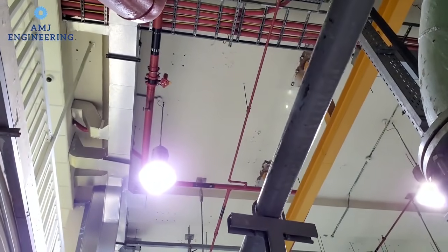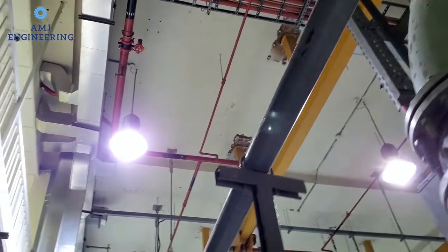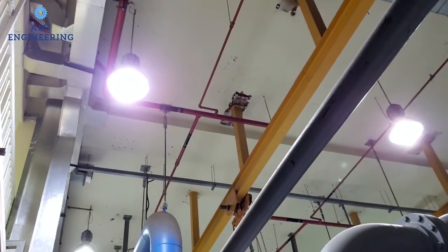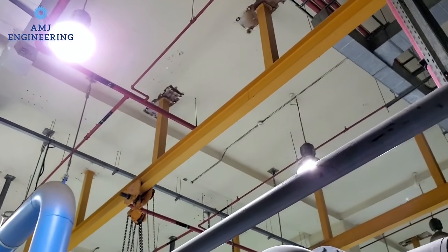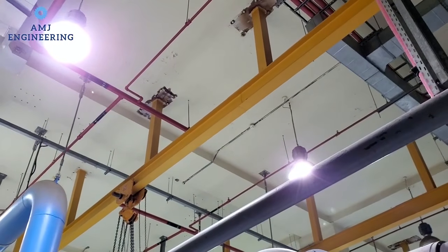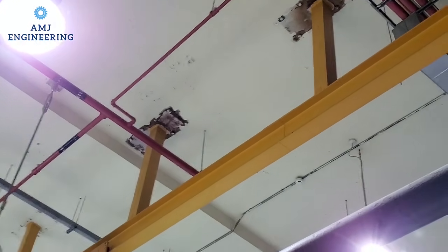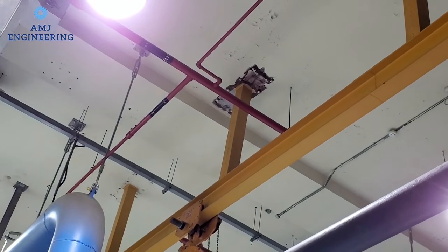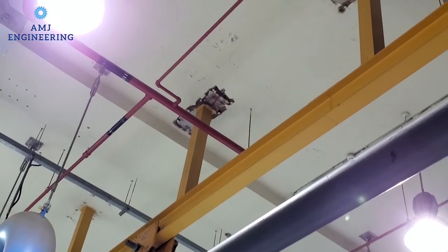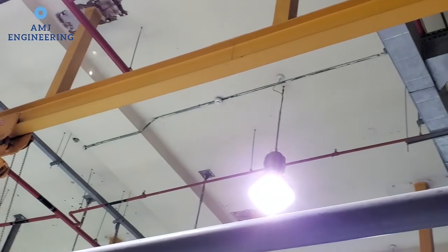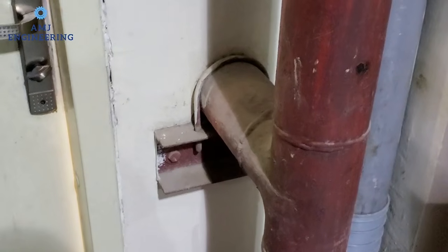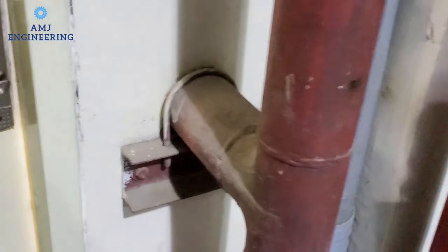There are 3 common reasons why this additional water supply may be necessary by the sprinkler system. A closed valve on the domestic water supply leading to the sprinkler system. Inadequate domestic water supply being delivered to the sprinkler system. A change to the occupancy of the building that presents a hazard greater than the sprinkler system was designed to handle. Let's go back to the branch feeding the landing valve.